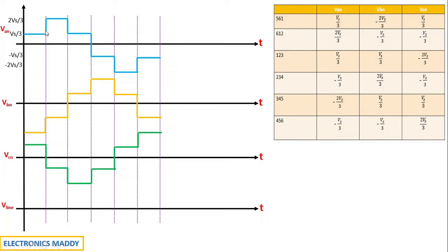That is something that you might have as a doubt, isn't it? Since we are using a resistive load, the variation takes place instantly. But if you are using an inductor, the change takes place slowly. We cannot write this as a rapid waveform. So it totally depends on your load. I've considered a resistive load, basically a star connected resistive load. As a result, the change takes place instantly. Hence it's a spike. It just changes rapidly. I hope this point is clear.